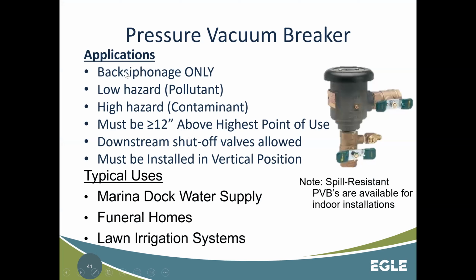So things to know about them. They are back siphonage only. They are used for low hazard and high hazard both, okay? They can be used for high hazard because if they're on lawn irrigation systems, as long as the pump is not downstream from it, but they have chemical additives, they are allowed because it's a high hazard application. You see these in marinas too and funeral homes, but lawn irrigation systems are the king of where you see these, just FYI, okay?